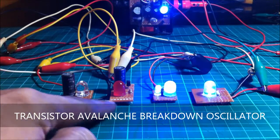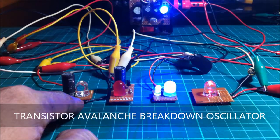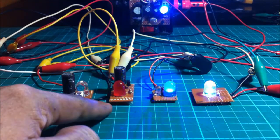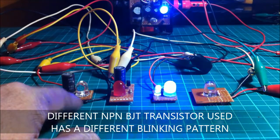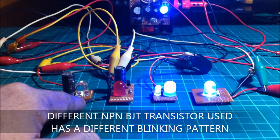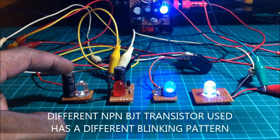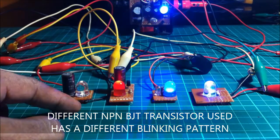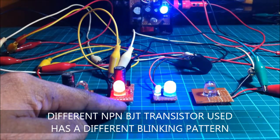Why is the blinking pattern different if they are both Esaki oscillators, or transistor avalanche breakdown oscillators? Because I'm using different transistors. This one I'm using a C1815 BJT. This one I'm using a 2N2222A.